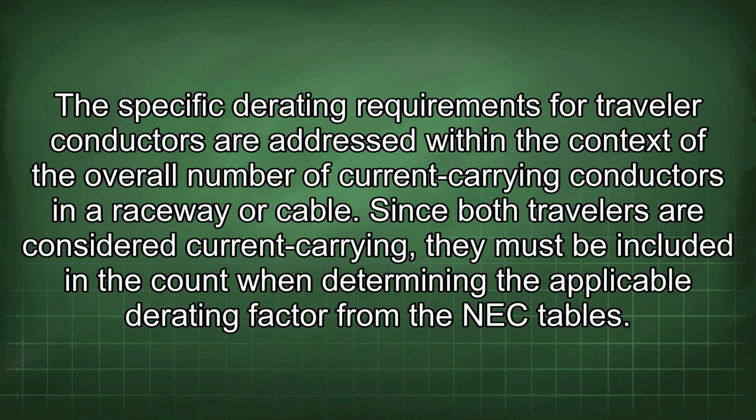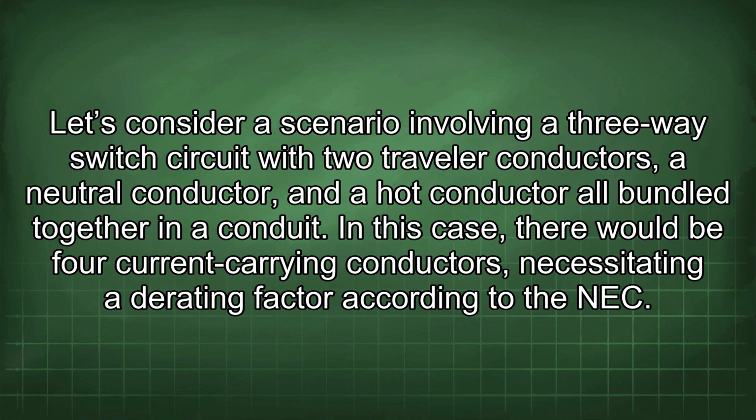Since both travelers are considered current-carrying, they must be included in the count when determining the applicable derating factor from the NEC tables. Let's consider a scenario involving a three-way switch circuit with 2 traveler conductors, a neutral conductor, and a hot conductor all bundled together in a conduit. In this case, there would be 4 current-carrying conductors, necessitating a derating factor according to the NEC.